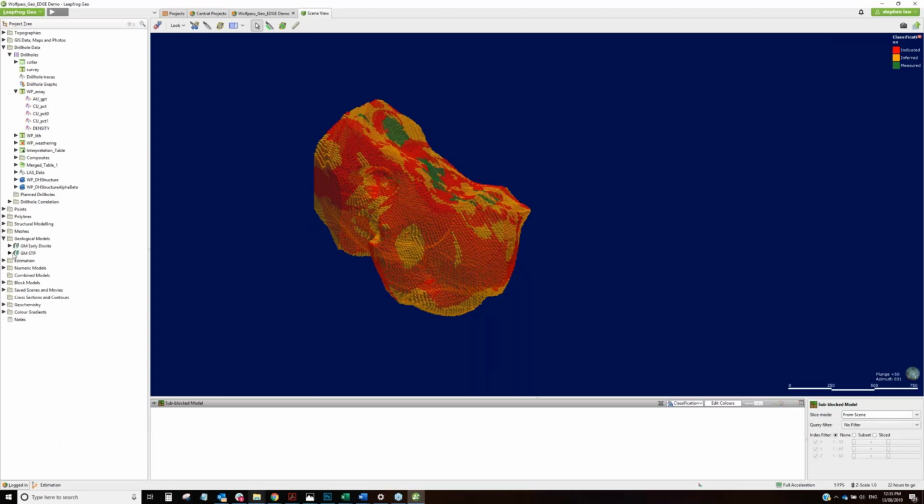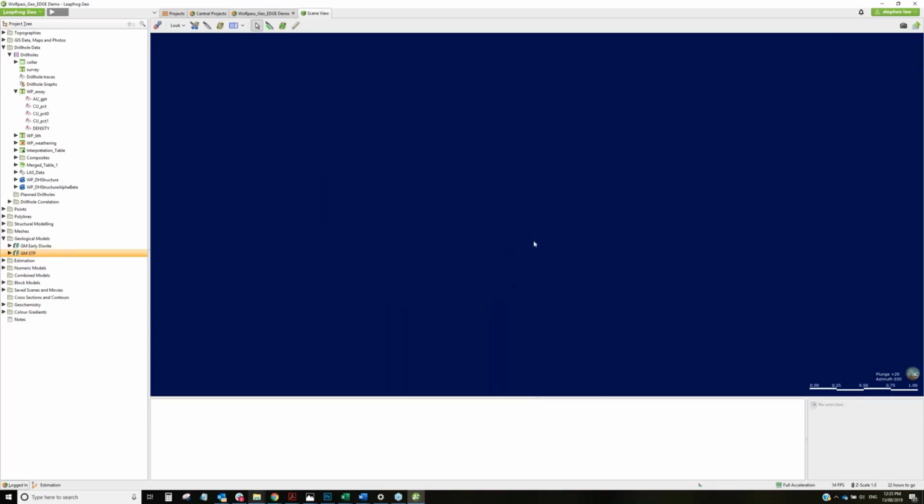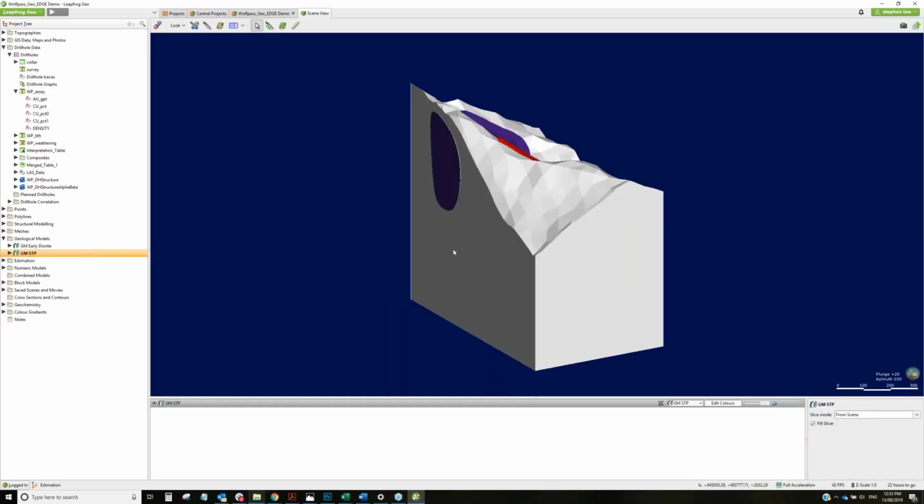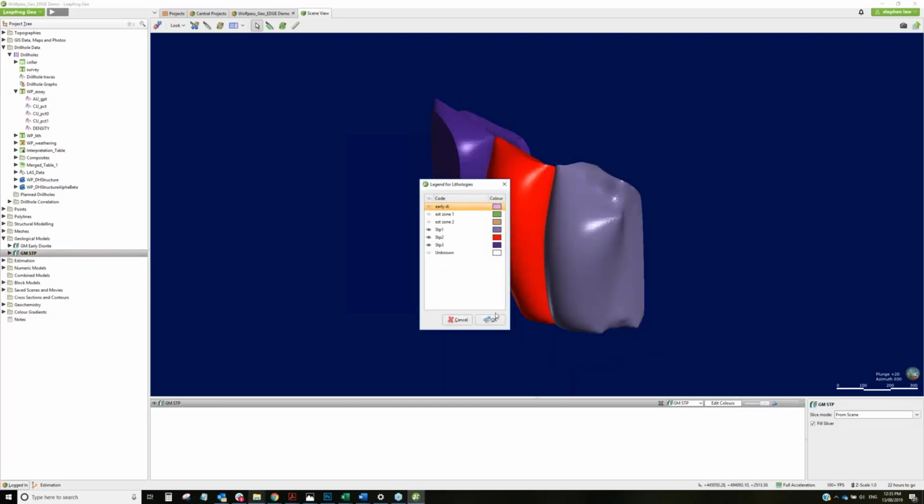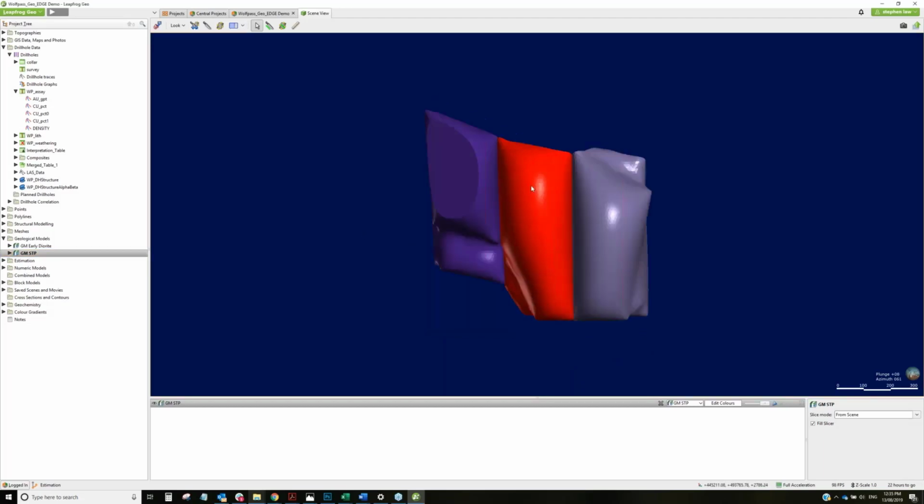So what I've done, as an example, I've got this stope model. So excuse the shapes, but we've got 3 stope shapes that I need to report on. So what I've done is built these into a geological model. It's a simple process, and we've actually got a blog that's coming out soon that explains this entire process, and this pretty much works for any kind of solids that you wish to report from. So if you've got classification solids, so you've got inferred, indicated shapes from another package, just import them into the meshes folder and then just build them in to a simple geological model.